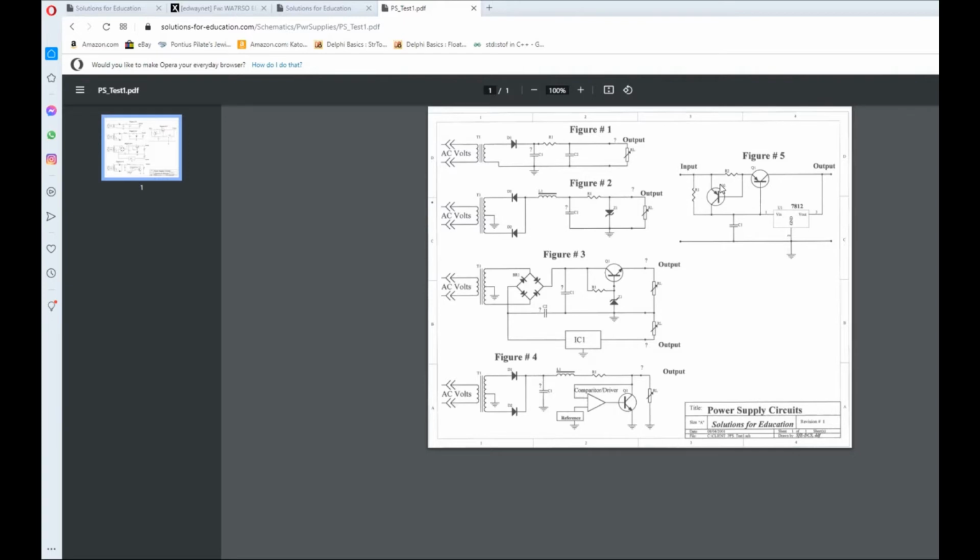Guess what? You could vary this, and you would vary, therefore, the amount of current limitation. In other words, if you wanted to limit this thing to 3 amps, never get up to 4 or 5 amps, what you would do is have more resistance here, because as the current goes through this guy, it builds up that base to emitter voltage and turns this guy on, which shuts this guy off. So, hey, there you go. That's current regulation. If you made this guy here variable, that tells this guy to start coming in either a little earlier or later, making this guy work for it.